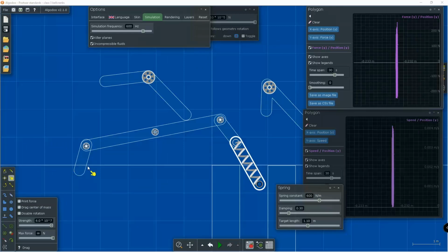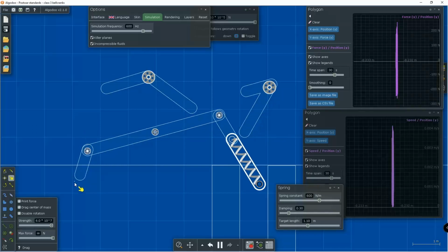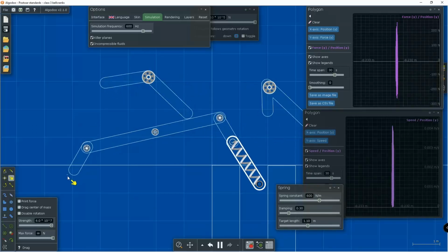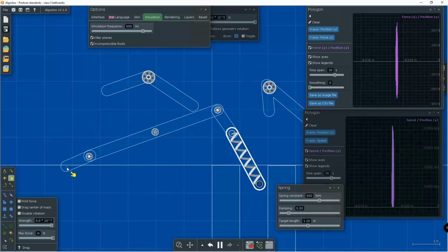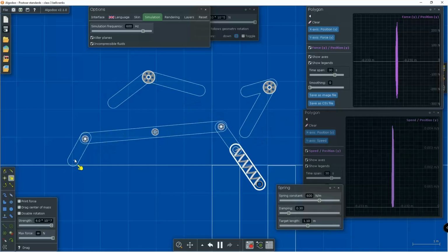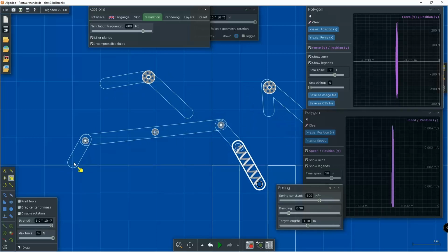Now, in the first special case, if we have a collinear, or initially what you would regard as a class 1 lever, but the effort and load force vectors, so here and here, are not parallel, then I would technically consider this to be operating as a kind of bell crank, since it is changing the direction to which the input force is being applied at the output.